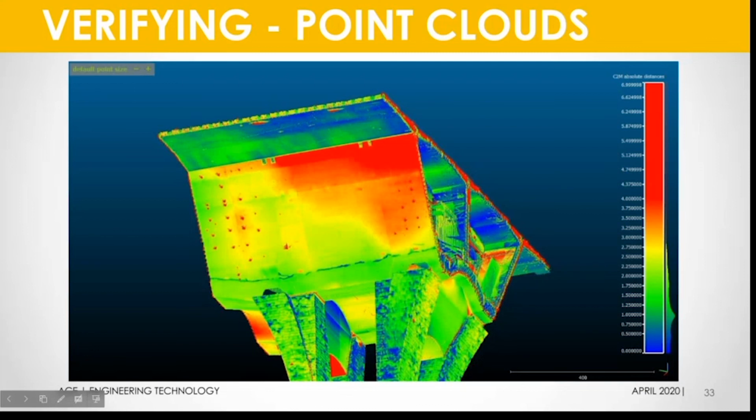So in this case, to actually verify that this really large structure was still within the allowable tolerances, what we did is we went out and laser scanned it and compared it to the model. And that's what you see here: the varying colors are representing how far from the design the certain areas are. So we could very quickly verify that all of the formwork and everything was moving and setting just the exact way that the computers predicted that it would.